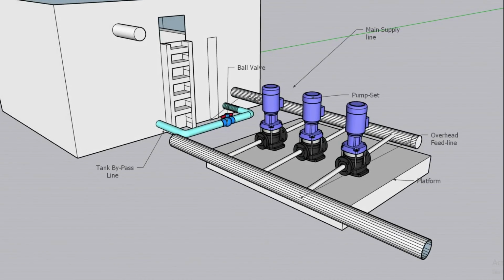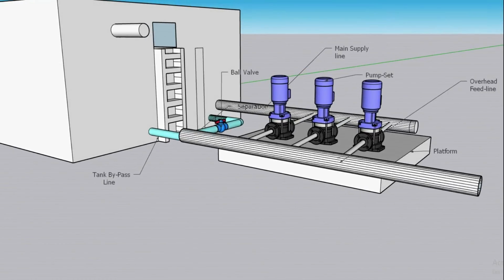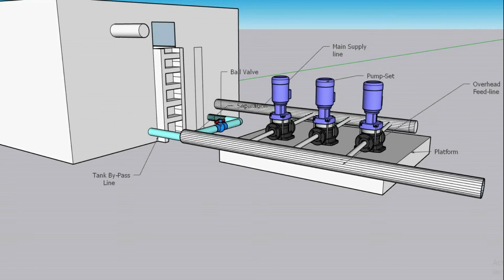Now, moving on to the pump set. This is a configuration of 3 pumps. So basically, there will be 2 duty and 1 standby. In modern pumps, we've seen pumps that have VFDs, pumps that will tell you exactly how much was the running hours. They're all configured together. There's new technology on and on.